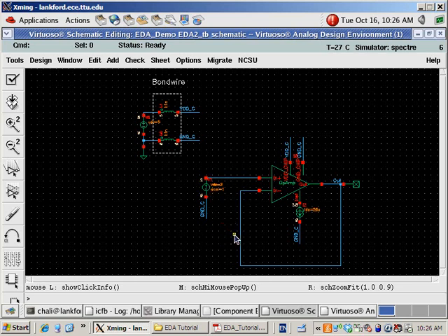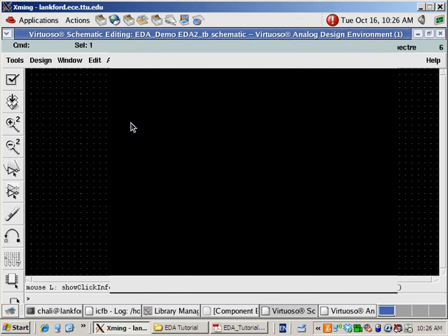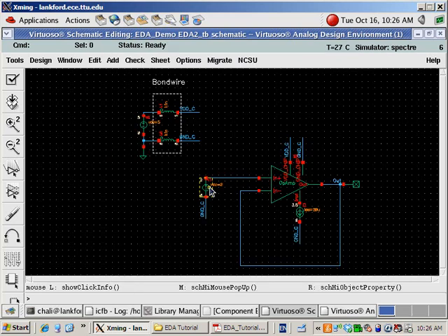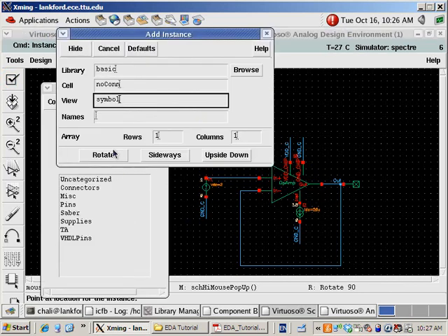So Cadence gives us a more powerful tool: we can use the stability simulation. In order to do stability simulation, first I'll delete the AC signal setup at the input side. Now we only have a 2 volt DC here.